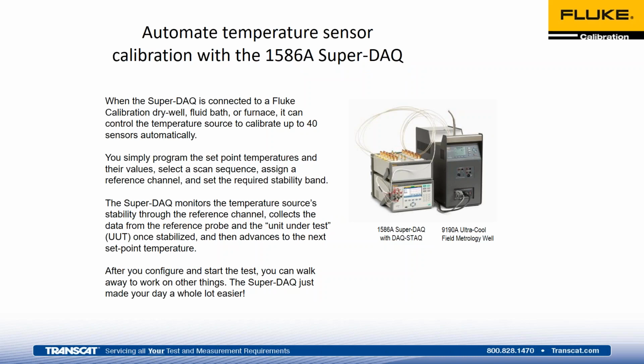All right, and this process actually can be automated. There's software that can do this. The one thing we have on our side of the fence that can automate it is our 1586 DAQ thermometer. It's got built-in software. It drives most of our dry wells and baths. So you can actually go in, set the units up, and then pre-program the data points with your stability and just let it go. It saves you a lot of time. You just come back, grab the data, and then crunch the numbers.